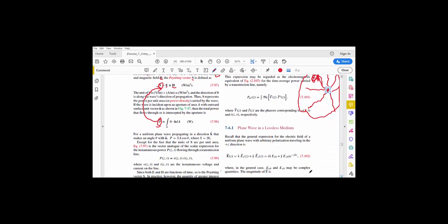So in this equation we could use the received power, or the transmitted power in case of isotropic radiation. For the received power, in any case, we could use the power density incident on any area or surface, and by integrating this power density over the area of this surface, for example an antenna or any receiver, we could find how much power is received or delivered to this device, component, or surface.